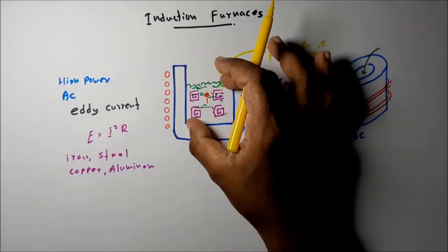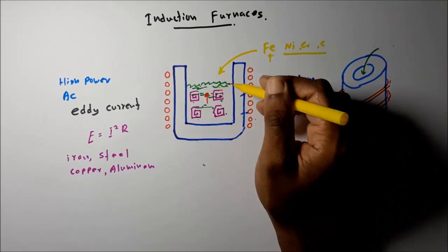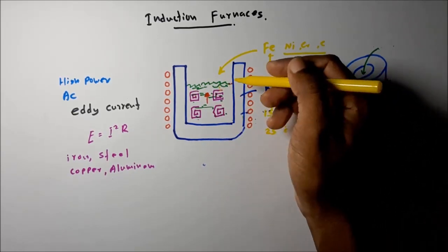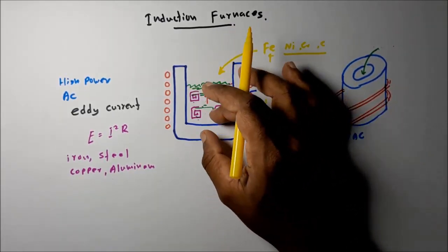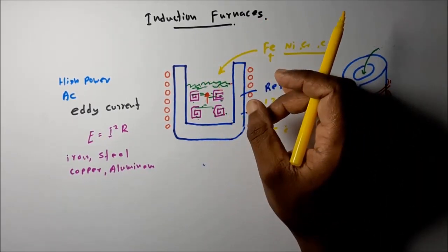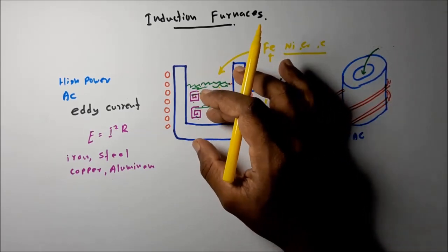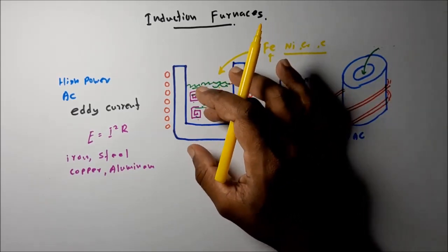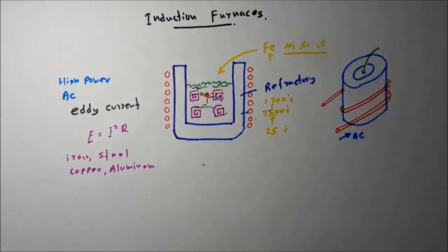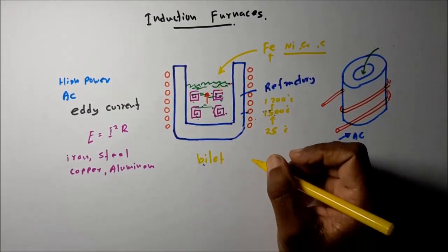It can also be used to melt copper alloy and aluminium alloy. When melting copper and aluminium alloys, the charging composition can be closely controlled, so a high purity product, that is, molten metal, can be obtained using induction type furnaces. Especially, induction type furnaces are used to manufacture billets for wire drawing.